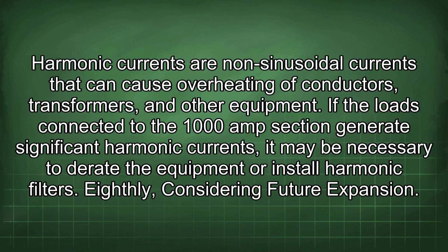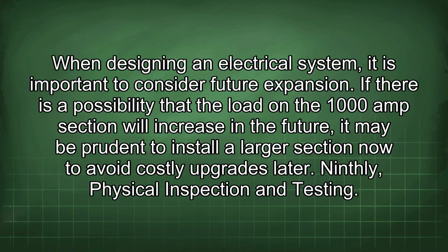Eighthly, considering future expansion. When designing an electrical system, it is important to consider future expansion. If there is a possibility that the load on the 1000 amp section will increase in the future, it may be prudent to install a larger section now to avoid costly upgrades later.